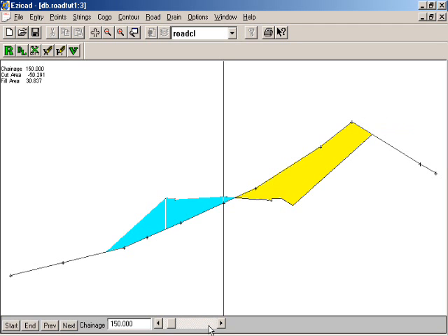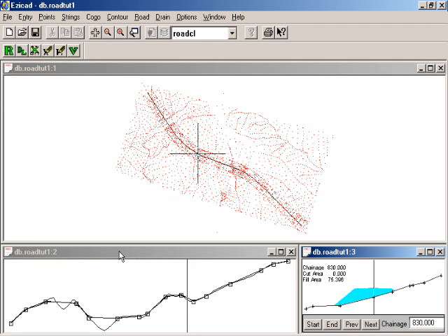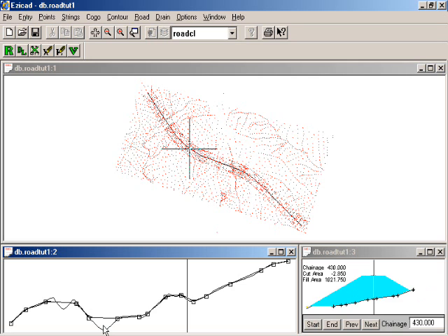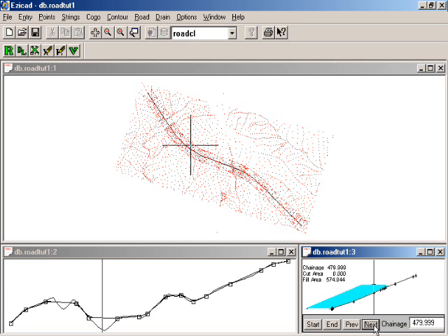Once you've had an initial look at the sections maximised, we suggest that you minimise that section window so that you can again see the 3 windows, and then proceed on to a complete review of the design as it stands at this point. The review process consists of looking along the length of the road and checking both the cross sections and the profile to ensure that there are no problems. Here you can see that we're obviously going to have some trouble through the major fill embankment, and we may have to reconsider that or put a bridge in.